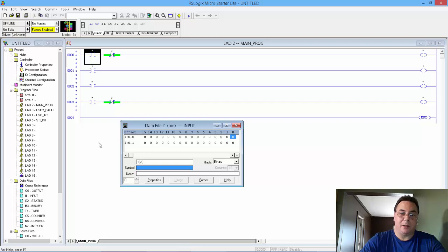The beautiful thing about this processor is, okay, it has 10 24-volt DC inputs available and 6 AC or DC outputs available, depending how you have it wired. The line voltage for the processor is 110 volts AC, and it actually creates its own 24-volt DC internally and offers it on a terminal on the input terminal side, so that you can tap off of the processor and power your devices if you so choose.